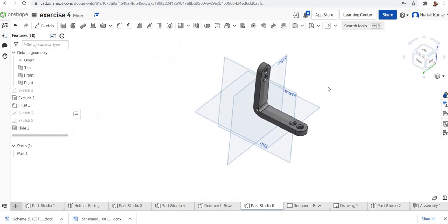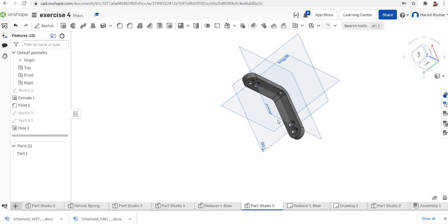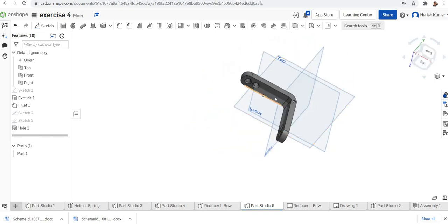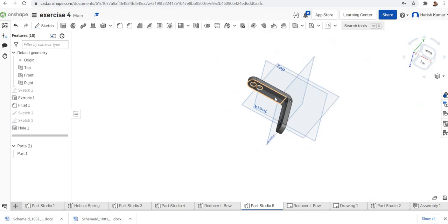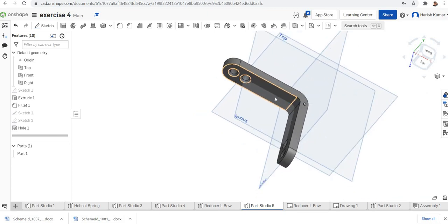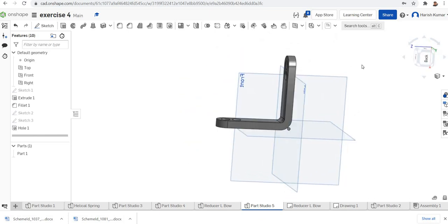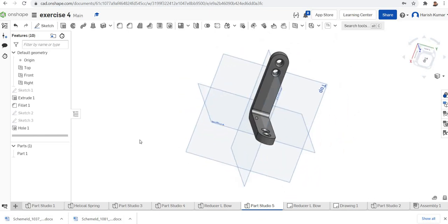So to rotate, you simply click the mouse and rotate. If you want to magnify, simply put a point there and move the mouse up and down. It gets scaled. These are the basic things you want to learn about the environment. I'm going to wind up this section now. In the next session, we are planning to work with 2D design, 2D drawings, 2D drafting.